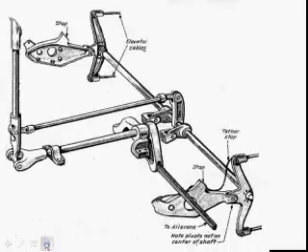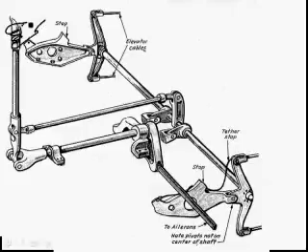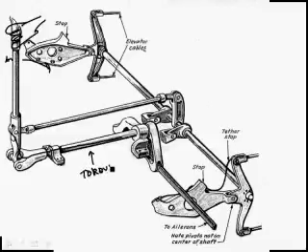Here's diagrams, got some push-pull tubes and stuff. So here's a control stick. We wrap our fingers around it, and we can go left and right with the aileron, and this tube right here is getting twisted. So it's a torque tube, and it's hooked onto this piece of metal right here, and now we have a push-pull rod that goes out to the aileron. It doesn't show it, but there's probably one going out there to the other aileron.